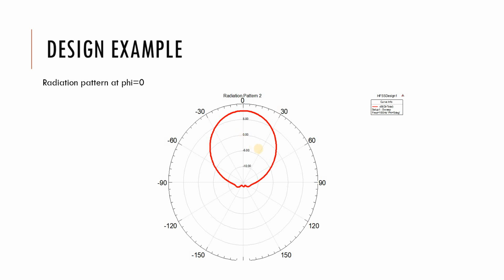And for the phased array antenna or in an array antenna, it's better to decrease the side lobe. There are some techniques and some complex structures that will decrease the side lobe level of the antenna, which is very critical in phased array antenna, in satellite communication, or in 5G application, to have the side lobe level below minus 30 dB, minus 40 dB, and something like that.